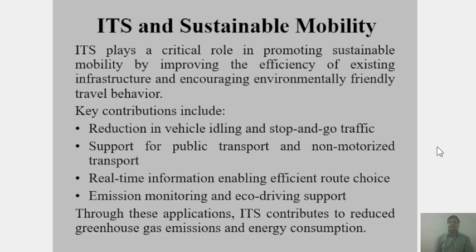So to promote sustainable mobility, ITS plays an important role by improving the efficiency of the existing infrastructure and encouraging environmentally friendly travel behavior. The things included are reduction in vehicle idling and stop-and-go traffic. If ITS is correctly implemented on the road, we can reduce the idling time of vehicles, so that fuel consumption can be minimized, and with stop-and-go traffic, signal coordination can be in proper position.